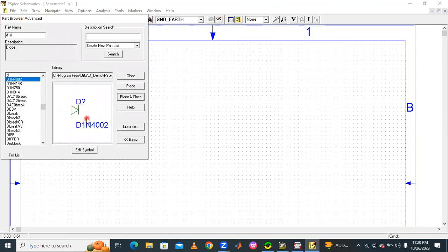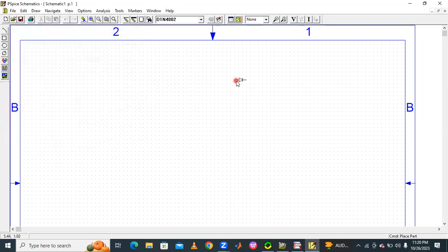So we have to understand the diode characteristics by placing it. Press Ctrl R if you want to rotate. Okay, like this. Place here first. The next is take one voltage source, VDC, and place here. Similarly, take one resistor and place here, and take one ground and place.